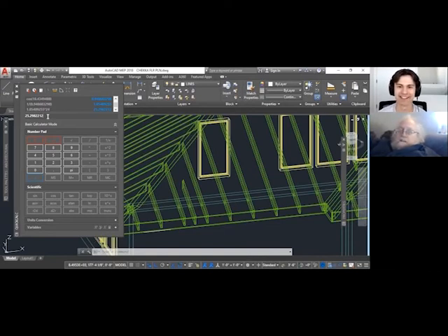That was my next question. So if you could say that again for me, how do you determine how many jack rafters you need? You just keep hitting the button and adding 25.298 inches to that. Once you get longer than the length of the common, which is way out here, anything longer than the common is too long. You delete that one, and the rest makes up your jack set.